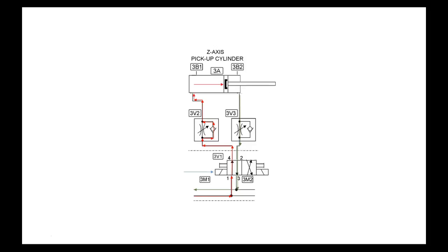Aren't flow control valves one direction though? No. Oh, they're not? No. And that's why in hydraulics, we'll put it on one side, and they won't be directional. So on hydraulics, we'll have a flow control valve over here on the exhaust or the input. Now, if we want it to move fast in one direction and control the speed in the other, then we will bypass it. We'll use a flow control with the check. So if we want it to move the same speed in both directions, on hydraulics, we'll just put a flow control valve. We won't put a check valve.